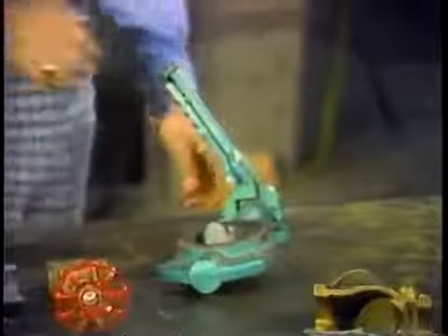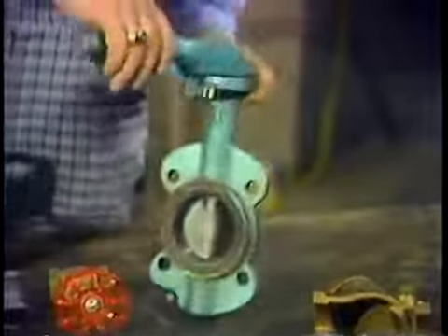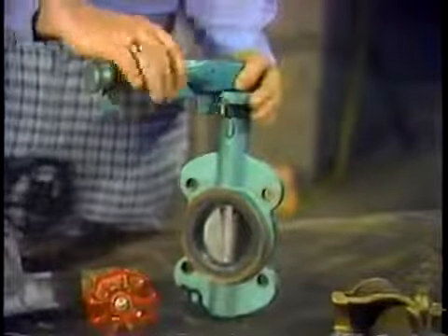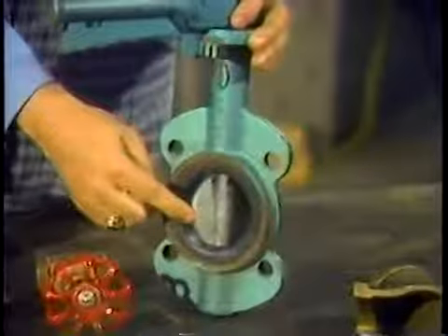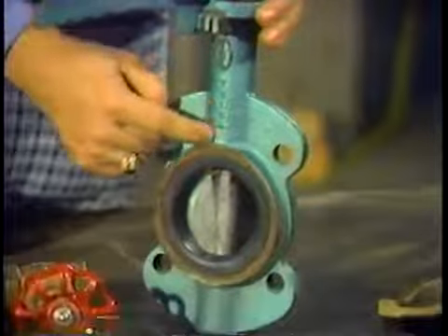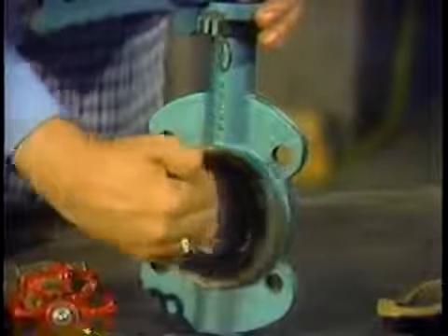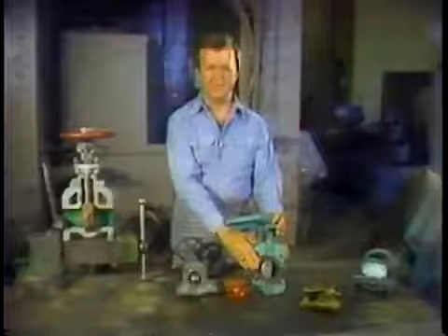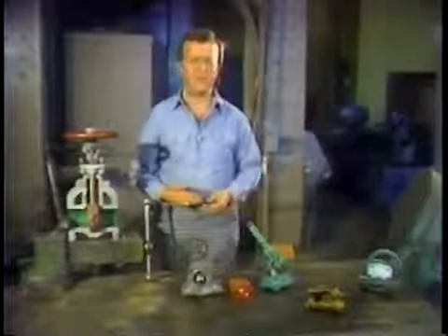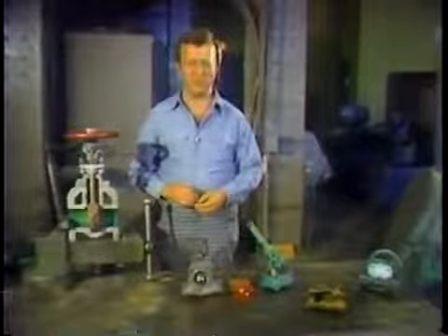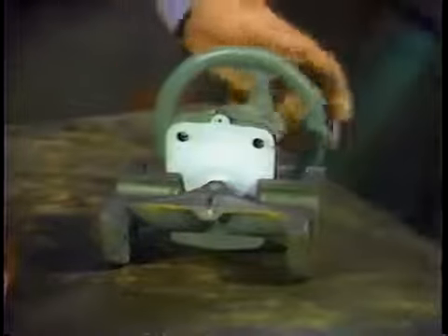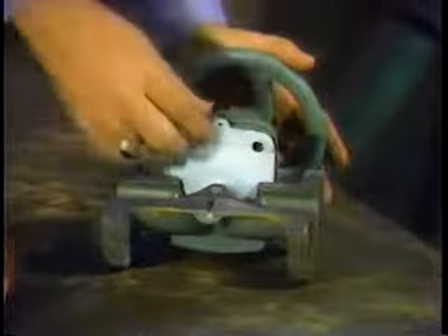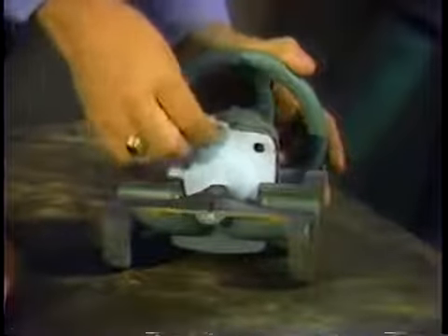Another type of valve used for isolation is the butterfly valve. Here, the disc is attached to the stem inside, and it swings open or closed. Butterfly valves are light in construction and are generally used on large installations where pressure is not high, such as a circulating water system. In a diaphragm valve, the disc is made of flexible material, such as rubber or plastic,